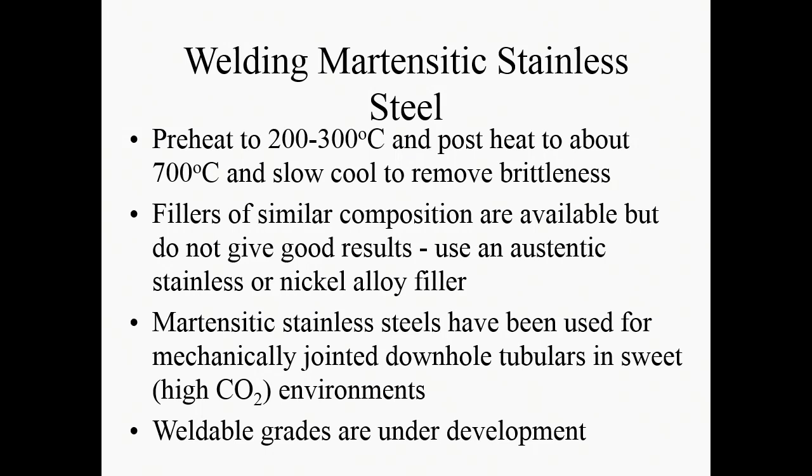Your hands have these larger gloves on, and I don't think it's something that I would want anybody to do, but it can be done if it's essential. You can use filler materials with similar composition, but they don't give good results. So generally we use austenitic stainless steel or nickel alloy fillers. So the welding consumable is expensive.